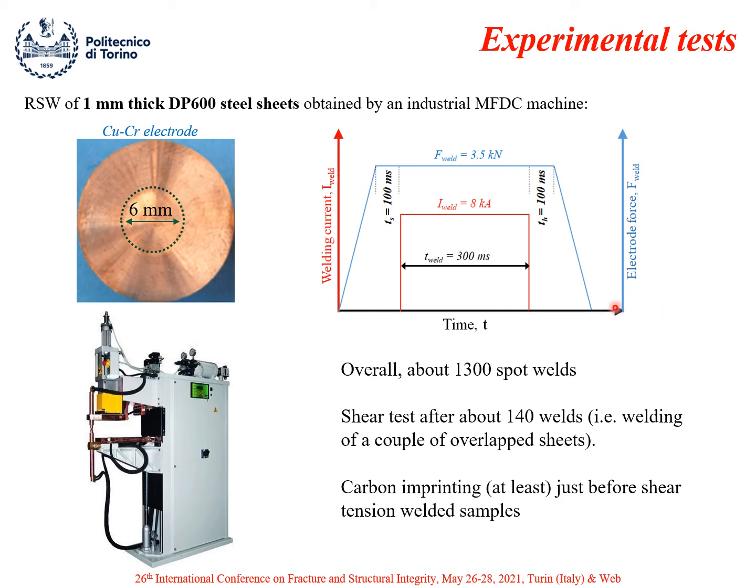And here you can see the welding cycle that consists basically in clamping the sheet stack with a force exerted by the electrode of 3.5 kilonewton with a welding current of 8 kiloampere for a time duration of 300 milliseconds.